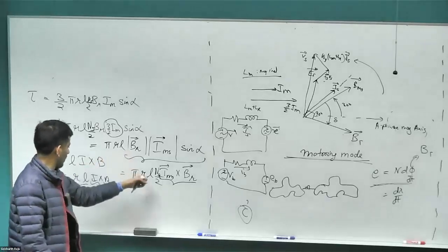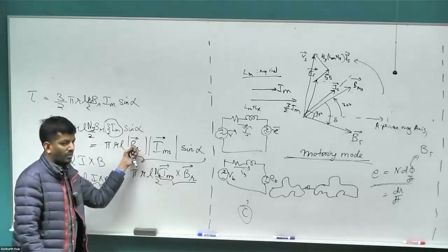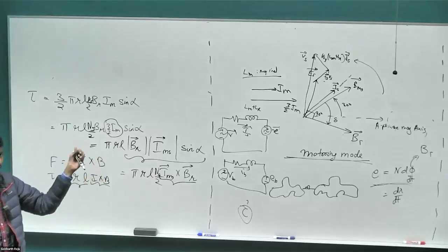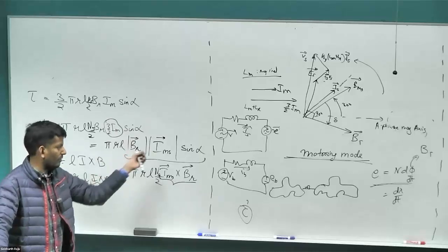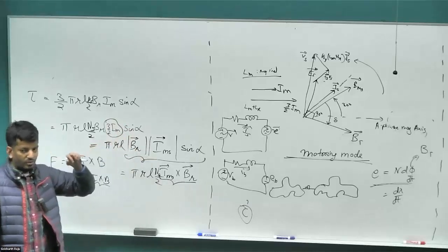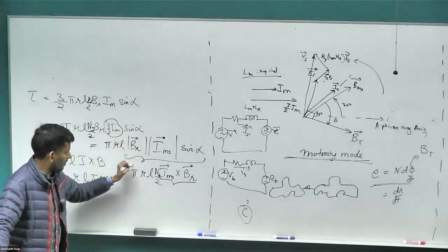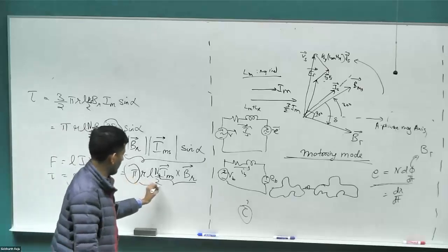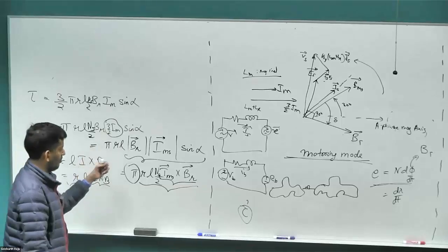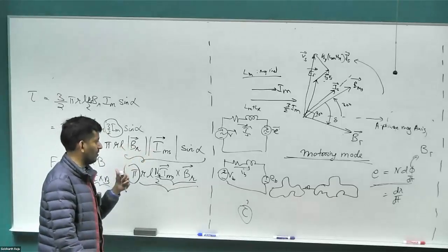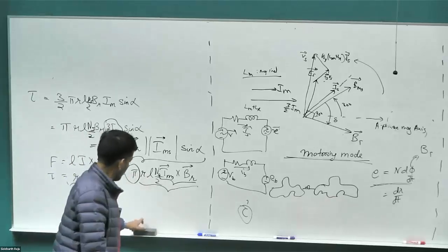In our case, the representation that we have here, we are just looking as if B R is some constant value, right? But that is not the case. B R is varying sinusoidally in the air gap as some function sine of theta. Our current space vector, again, a conductor density, is varying sinusoidally as sine of theta across the air gap. So you have product of sine of theta, and the average of it when you integrate it will give you the pi factor that's coming here. So this expression captures as if the current and the B R are constant at every single location, which is not the case. We have sinusoidally distributed both B field as well as the current density distribution. So that when you do the average of it, that will give you the pi factor that we have. Okay.